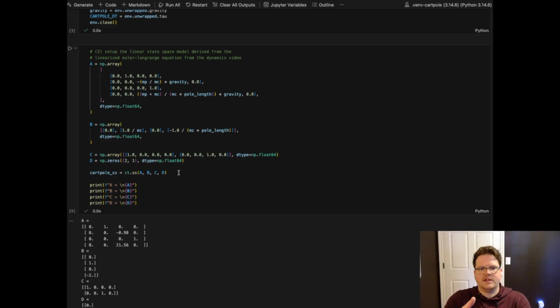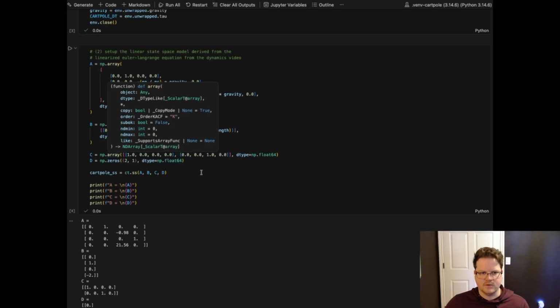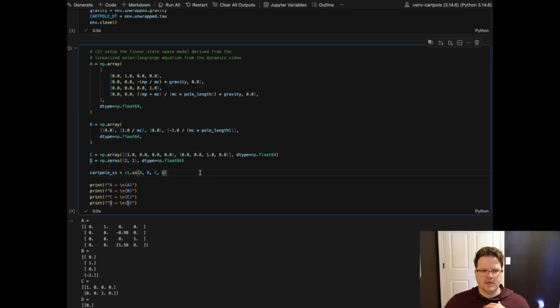This is taking that next step of essentially saying we have a sensor on the cart position, we have a sensor on the angle of displacement, we can observe basically, we'll see observability in a bit, but from these two sensors we can extract and get full observability on our state space with the X dot and theta dot, just with these two measurements here.